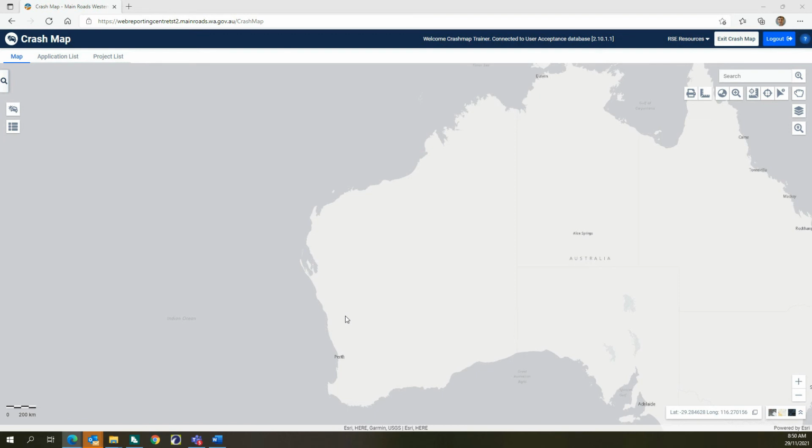an inspection-based blackspot application. First, it is important to understand how the crash risk score algorithms work in CrashMap for blackspot nominations that are based on a road safety inspection report when considering which location to investigate for potential treatment. When considering locations for treatment, you should consider the following. First, you should be looking at the locations that have just missed the BCR warrants for the federal and state crash-based programs. This is because the risk scores give a higher priority to locations that have a BCR that just falls below the crash-based warrants.